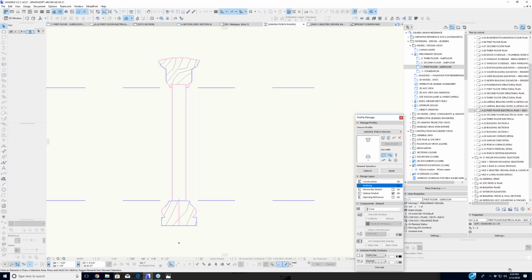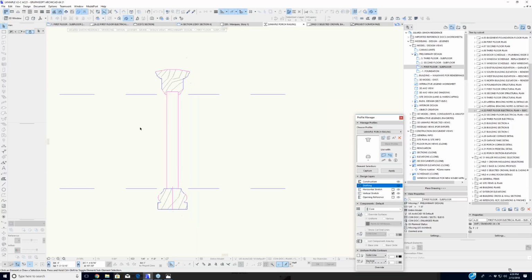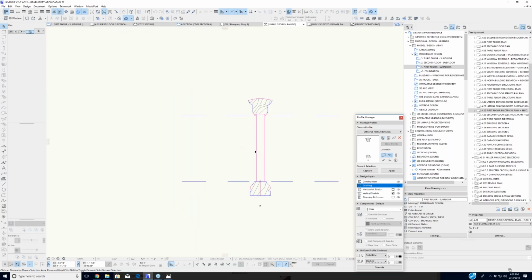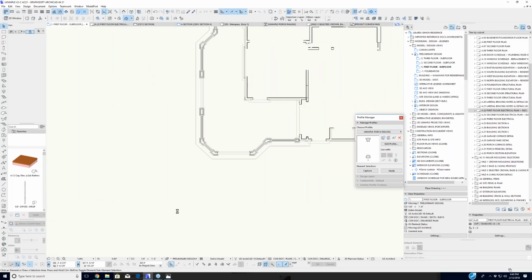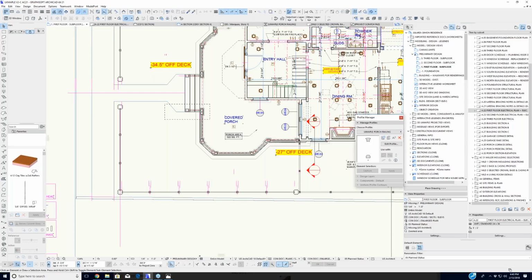Just as a side note, from what I can see, you could model this now with the new railing tool because you can pick balusters as objects. So in other words, the objects that you had there, instead of repeating them manually, they can be in the railing tool. Yep, you can also have whatever complex profile.